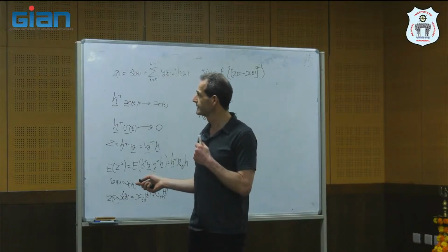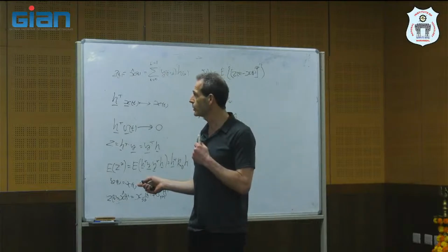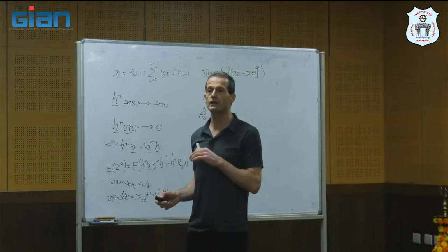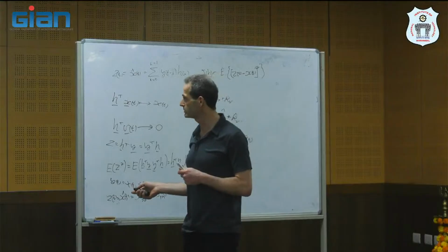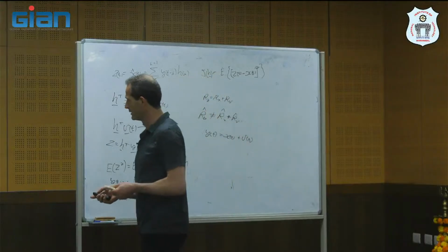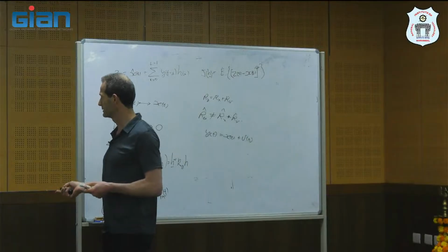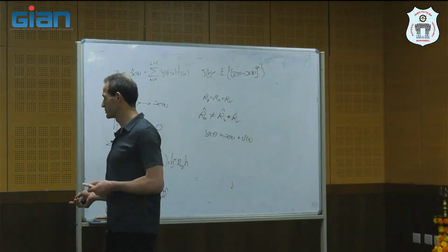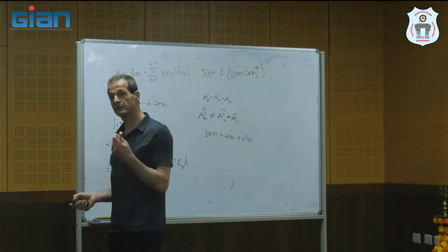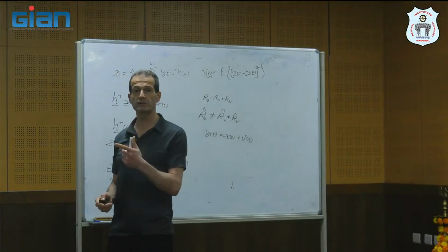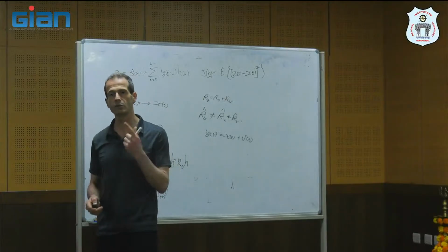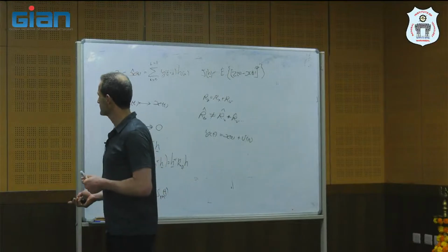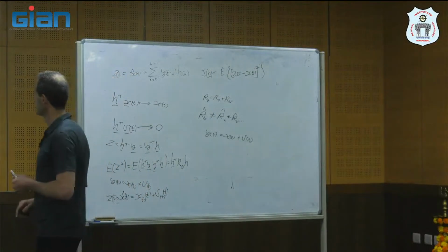So it's possible to prove that with the Wiener filter, the output SNR is always larger or equal to the input SNR. So we don't reduce the signal to noise ratio, which is important. It's possible to prove it. I will not go through the proof. You can read, and it's straightforward to see it, but it's an important feature that the Wiener filter does not reduce the output SNR, because the SNR is also important. So this is the proof. Okay.